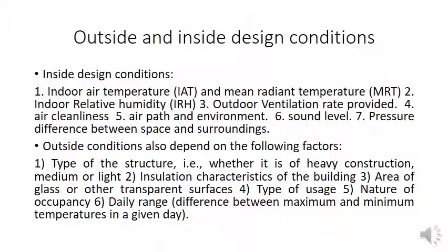Next is the pressure difference between the space and the surroundings. Space means the condition in the space which is required to be air conditioned, and the surrounding means the outside surrounding. If a single room is there, then the outside air will be considered the surrounding, and apart from the wall, the internal space will be considered as the space. So the pressure difference may also affect the inside design conditions. So pressure difference, sound level, air cleanliness, air path environment, ventilation, and temperature and humidity, these are the inside design conditions. Basically these are the parameters which are required to be evaluated while discussing the inside design conditions.